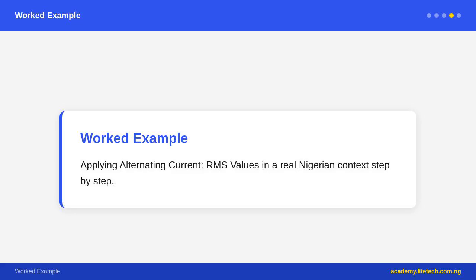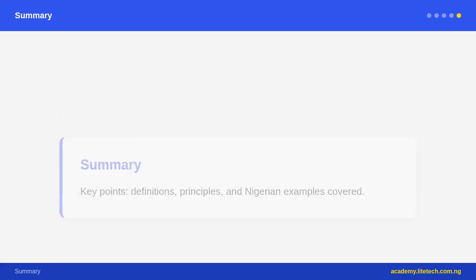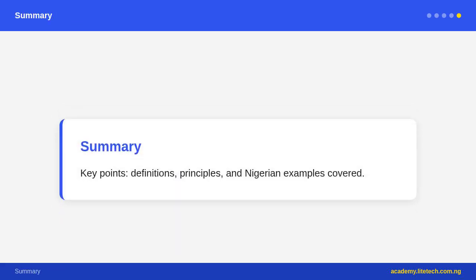Average output voltage equals V0 divided by pi, which is almost equal to 0.318 times V0. Full wave rectification uses 4 diodes in a bridge rectifier configuration. Both halves of the AC cycle are converted to DC, the negative half is inverted, so output is always positive. Average output voltage equals 2 V0 divided by pi, which is almost equal to 0.637 times V0.